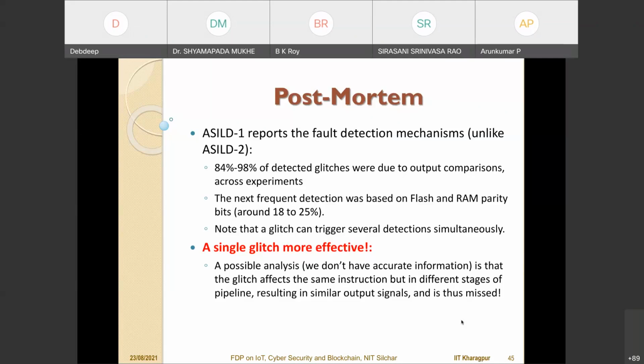But these fault injections essentially bypass the detection mechanism, because the fault detection is probably being done by implementing a three-stage pipeline, and the idea is that every instruction is performed once and again subsequent to that, to ensure that the computations are the same in both successive instructions.